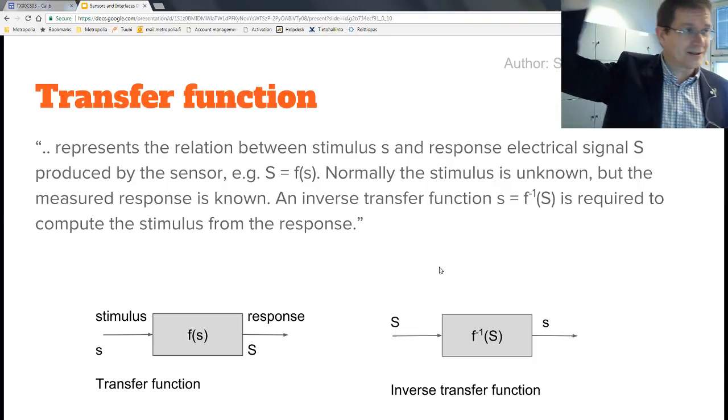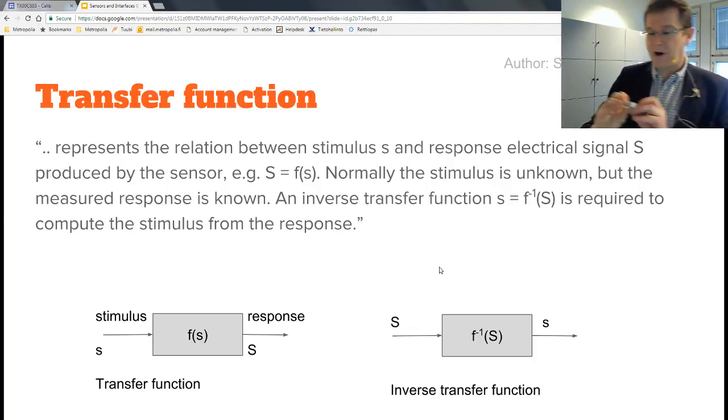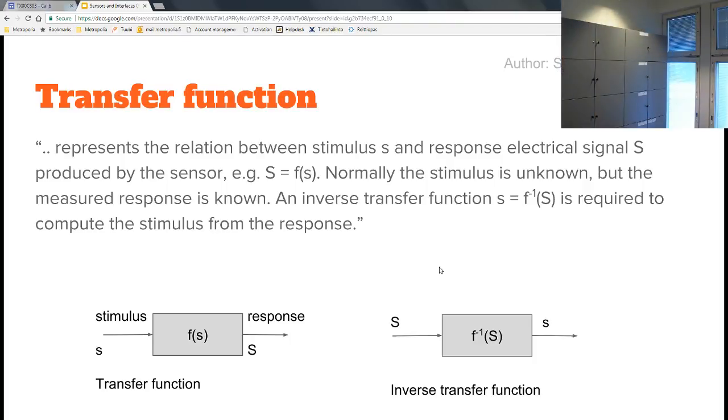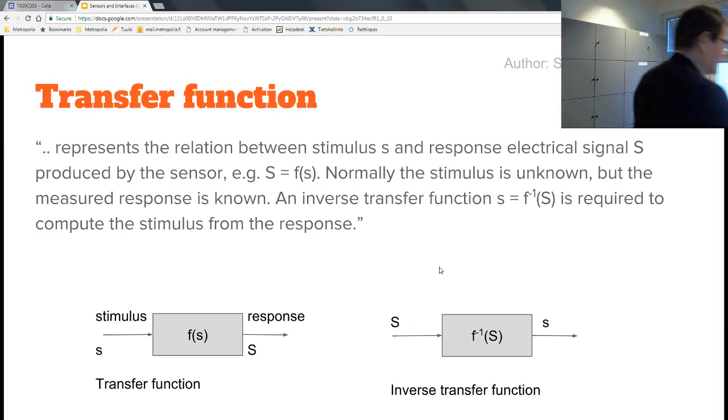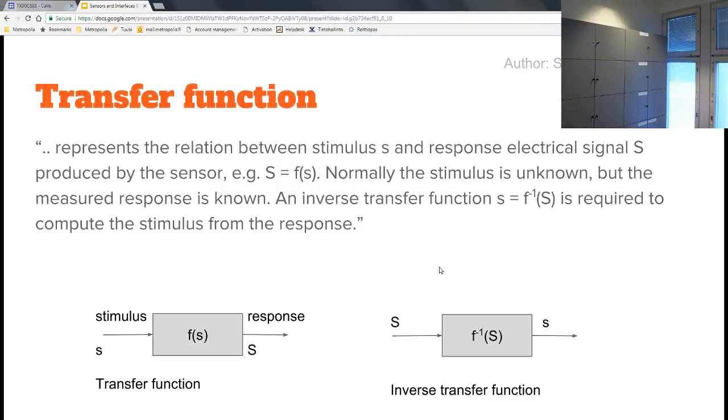Ultrasonic sensors that by default will give some non-linearity when you are close range. So we probably can see some funny results, and not only close range, but I would guess that there is also some skew on the signal on the far range. So I'm quite sure that we are getting a non-linear effect from this sensor.